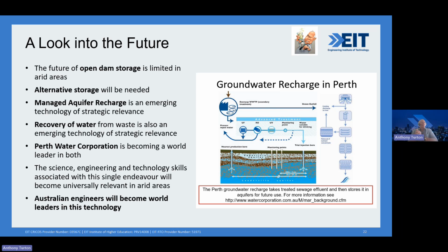So, making some forecasts now about the future of engineering in these kinds of economies. The first thing is that open dam storage is limited and becoming increasingly irrelevant in these arid areas. So we've got to start thinking about things other than open dam storage. That's the cutting edge for engineers to start thinking about, start positioning themselves for career development, think about things other than dams. Alternative storage is needed. And one of the best alternative storages here is something that's being actively worked on here in Australia, managed aquifer recharge or aquifer storage and recovery.